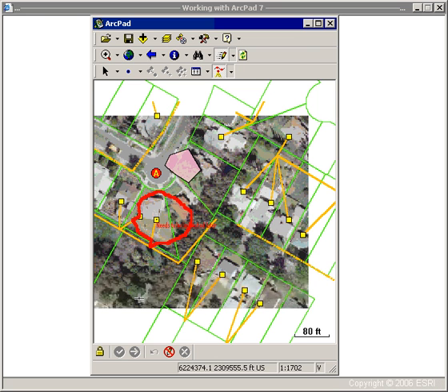This graphics layer can be easily imported into ArcGIS and then be shared with other users as well. In this demonstration, we showed some ArcPad editing tools using GPS, pen, or rangefinders. We use snapping to ensure correct connectivity of features, and graphics layer to add some field notes.